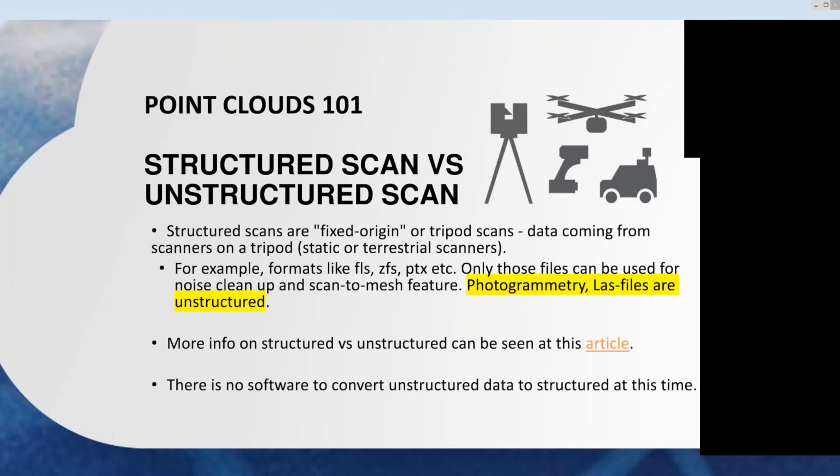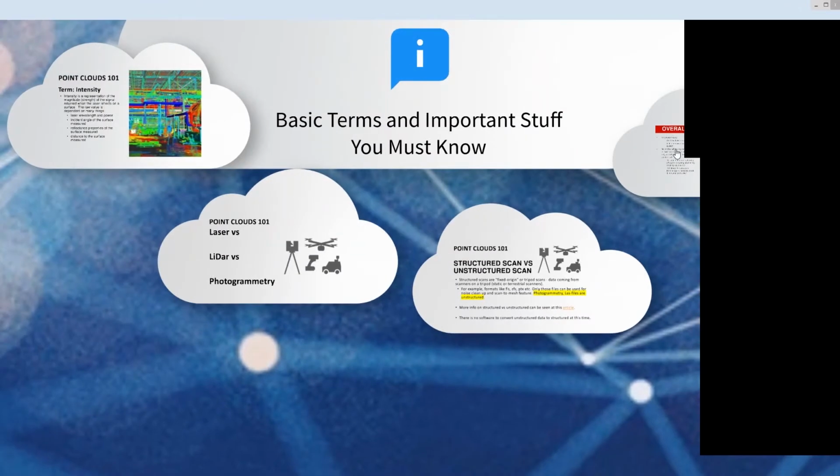An unstructured scan is something that's created, for example, for photogrammetry, so it doesn't have a real structure to it. So if the tool isn't working for you in the scan, it's not because the program's broken, it's probably because of the scan information. So it's really good to know where the scan came from, what they used to create it, what kind of coordinates it's in, and to ask for that information.